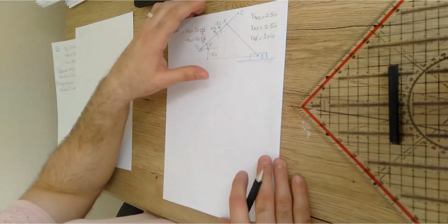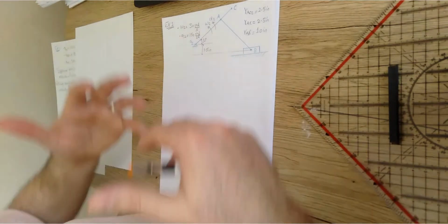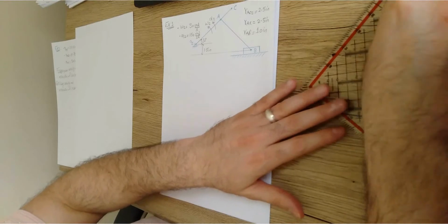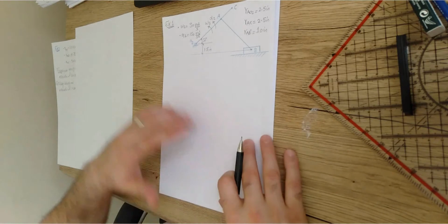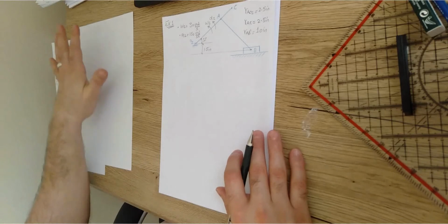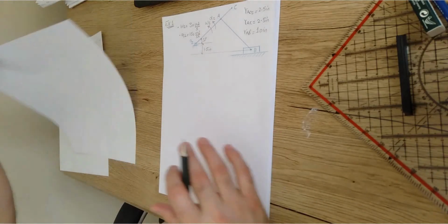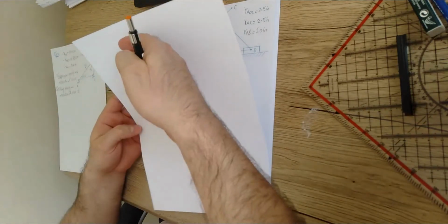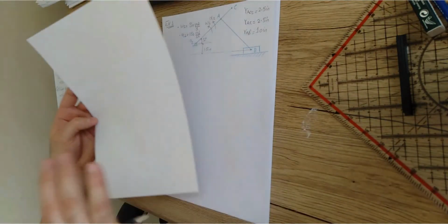As you're gonna see now for the velocity and acceleration analysis, we're gonna plan how we are going to draw these velocity and acceleration polygons. So we're gonna put the plan and all the details and all the calculations over this sheet, but this other one we're just gonna save for drawing. Everything, all the polygons should be represented over the same sheet. It is not possible for you to represent the position polygon in one sheet and the velocity polygon over another sheet, because you need the position polygon to generate the velocity and acceleration. So all of them should be represented over the same sheet, as I'm going to show you.